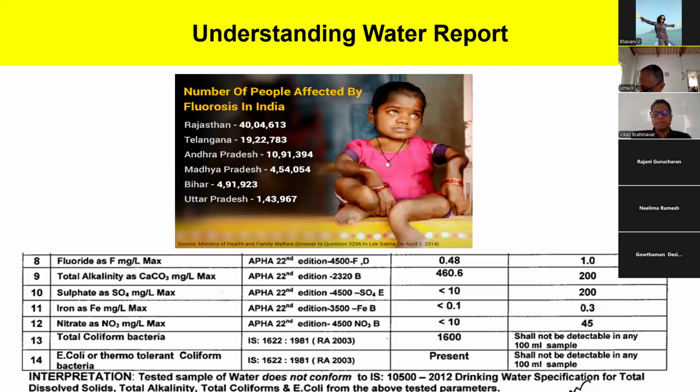Now, these are the standard parameters. As per IS 10514, these parameters at minimum have to be tested for any water. The general frequency in Bangalore is at least once in 6 months, if you are using borewell water. If it is municipal water, most of these parameters are in range, but it depends on the region. I'll come to those slides a little later. But if you're in the core region where the pipeline work is done and you have consistent water supply quantity and quality, then Kaveri water has most of the parameters addressed.